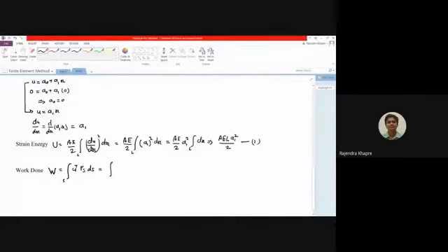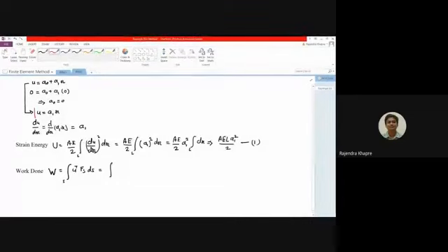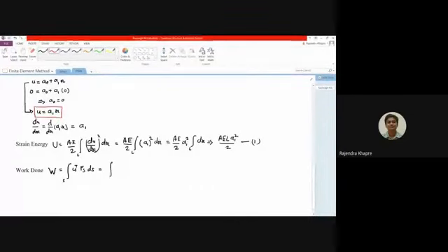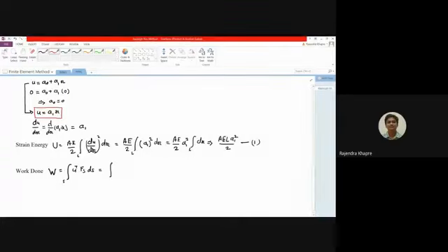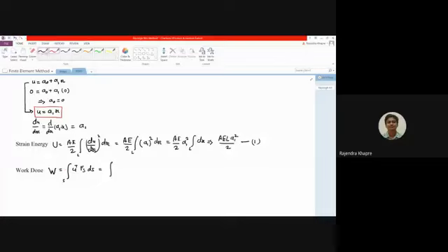Okay, so now what is my U transpose? Just now we have seen this is the expression for displacement, that is u equals a1 into x. So I am going to put the same expression in the integration part over here. Again I have missed this negative sign, because in yesterday's class, if you remember, the work done has to be taken as negative. So this will be negative. So here I am going to put U transpose, so a1 into x. It's a simple 1 by 1 element, so its transpose will be exactly the same.